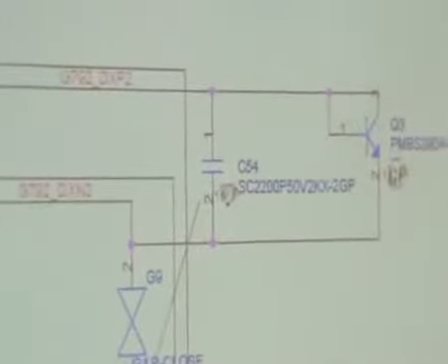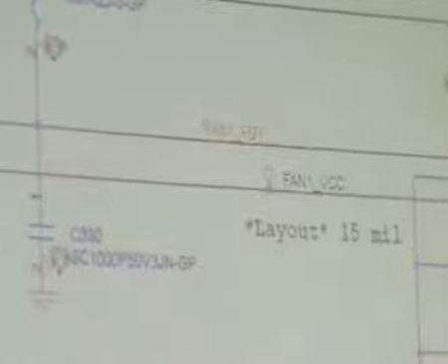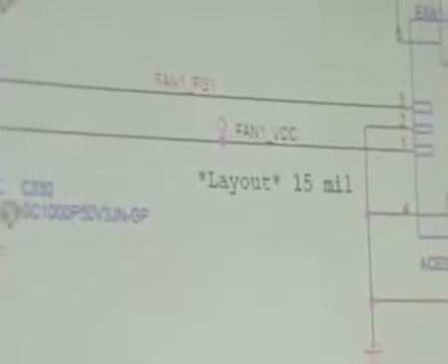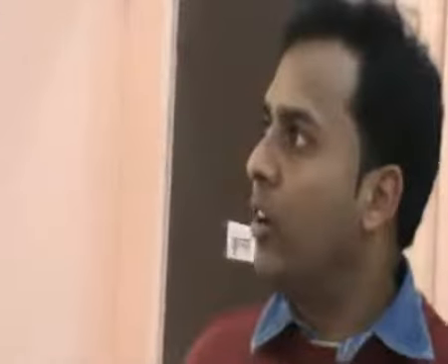If the CPU releases this signal, then this controller will release the fan signal to the fan controller. Here, this signal is coming to the fan controller. Then this CPU fan will operate, so the CPU fan will start moving. When your processor doesn't get appropriate heat, this signal won't come over here, and this regulator won't generate the fan signal, and so your CPU fan won't run.